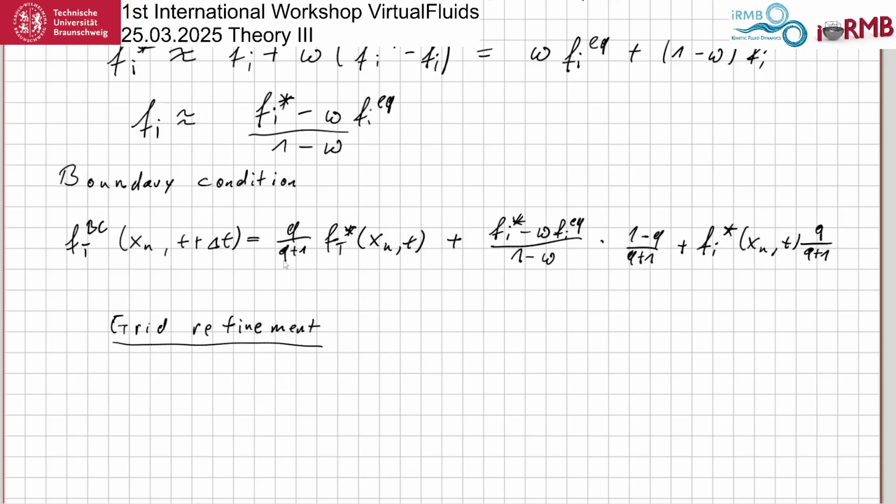So first of all, if we do grid refinement, at least if we do this in VirtualFluids, and I would say that 95% of the Lattice-Boltzmann world agrees on that point, we use acoustic scaling. Delta x is proportional to delta t, meaning that Cs is constant.